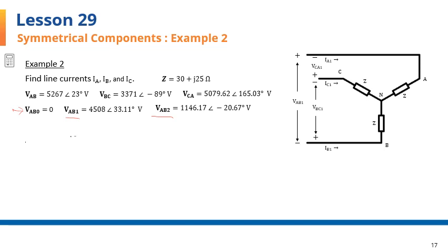Reasoning about the three components of the currents into the phase loads, it is clear that the zero sequence set of currents has to be identically zero due to KCL, because their sum as they flow into the neutral point has to be zero, and since they are identical to each other, then they each have to be zero.